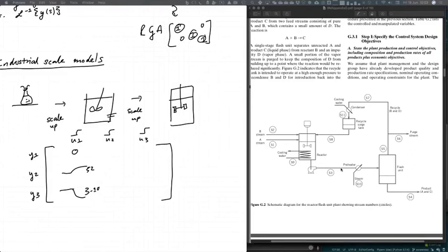Effective control valves have large pressure drops. Large pressure drops in this line means that this pump is going to need to be bigger than it would otherwise have been, which means that the capital cost of the plant is suddenly bigger, right? So there's a subtle interplay between the designers of the physical hardware and the control designers.